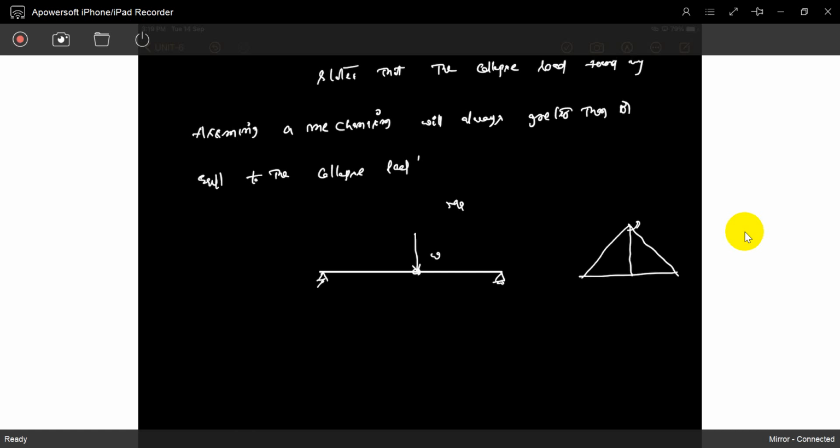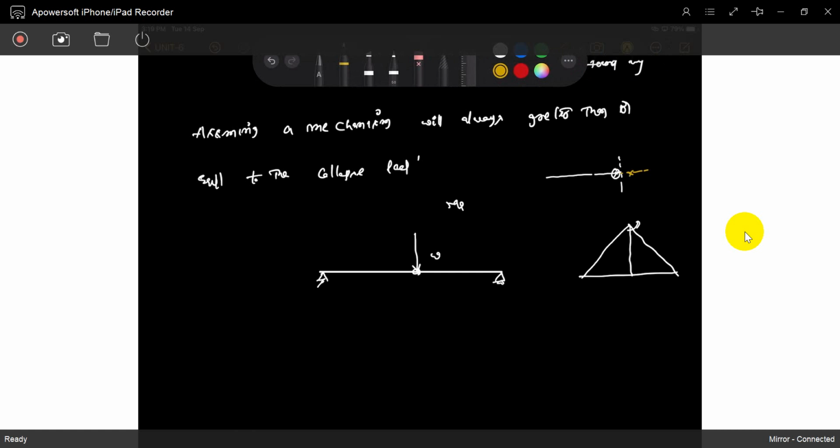Previously we applied the load just before the collapse load. Just reaching the collapse load, we took the bending moment diagram. Now we take it just after reaching the collapse load. Sir, once it reaches the mechanism, what happened? It formed a hinge. Once a hinge forms, it goes like this, unstable. It just entered an unstable state. It gives deflection.